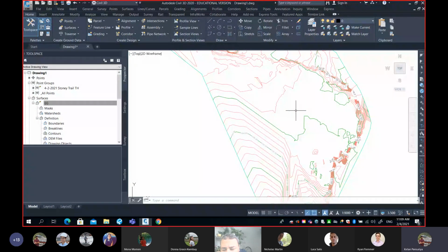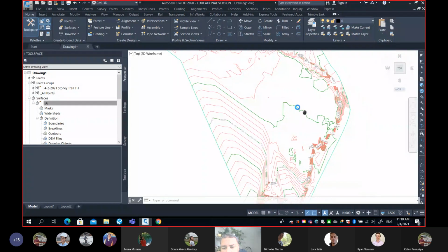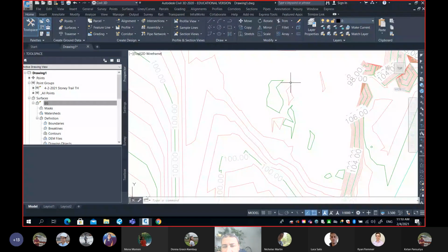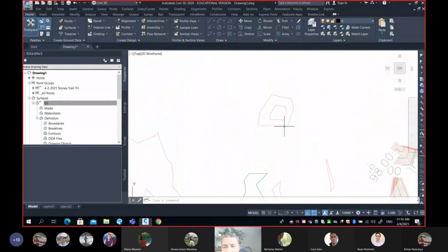Now, the last thing I want to show you before we move to another topic is something called spot elevation. Spot elevation is not the first time. If you go back to, I think, 2 lectures ago, where I showed you the contour map, I'm asking you here, if I printed this map, can anybody know what's happening in this area? You have a closed contour line, and those are minors, so there is no number. Would anybody know if this is a summit or depression?